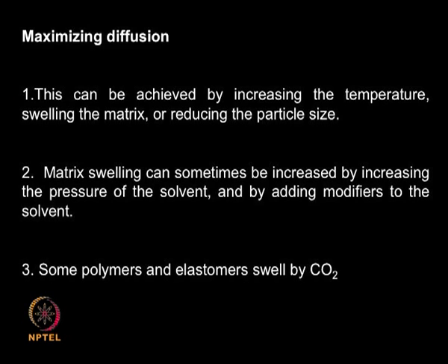So how do you swell the matrix? So we can increase the pressure of the solvent, we can add modifiers and so on, so that the solid matrix gets swollen. Even some polymers and elastomers can be swollen by carbon dioxide actually. So if you have polymeric material, the supercritical CO2 will swell that matrix.